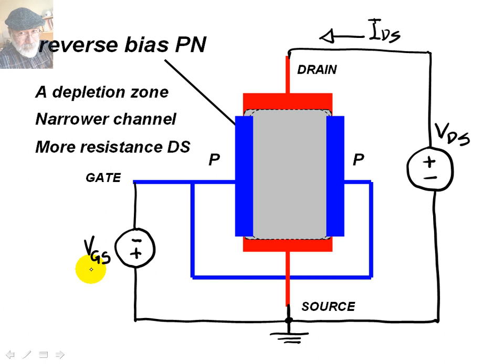We call that specific value of the VGS the pinch off voltage of the channel, or the VGS off value of voltage of the gate source. That is an important parameter in this new device. We are specifying the VGS off. How much reverse voltage we need to apply between the gate and the source to cut the current in the channel.